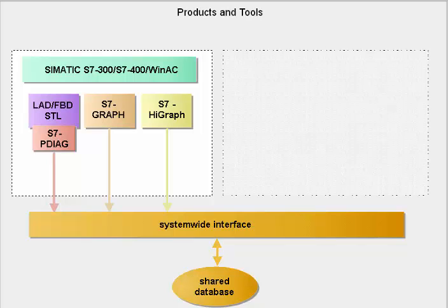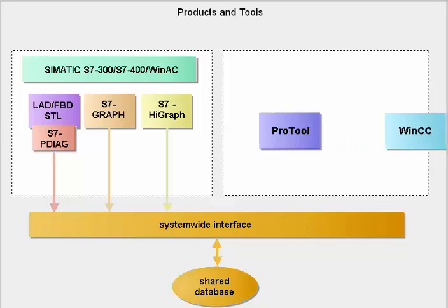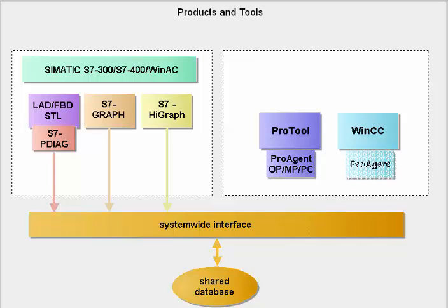The visualization tools ProTool or ProTool Pro and WinCC are enabled in each case by the ProAgent option package for seamless integration of the process diagnostics into the HMI system. This contains ready-made and pre-connected standard pictures which, with a minimum of configuration, integrate the complete function sequence for process diagnostics into the HMI device concerned.